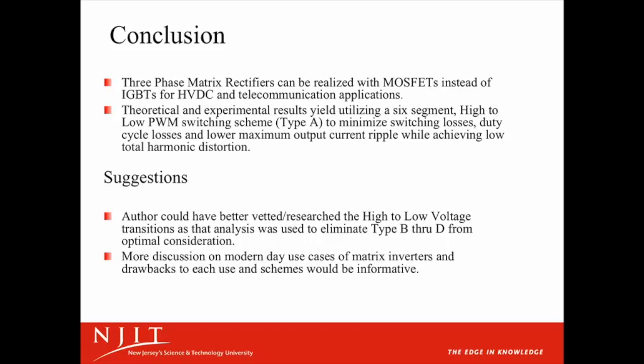What that gives us, using this type of matrix rectifier, is a variable voltage output. Right now we're using 280 DC volts, completely DC, and through that we invert using the same type of converter, just in the opposite way, as an inverter, to drive electric motors. What this does is we've seen an increased efficiency on the overall system from the low 80s to the mid 90s.